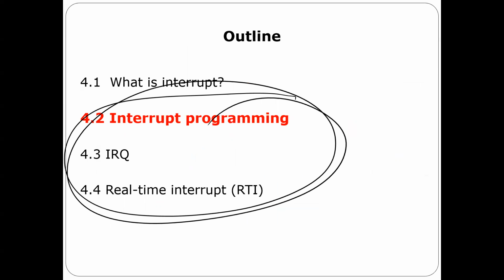if you compare it with what I did in chapter 3 in flashing the LED, it's going to be too simple now, because all I'm going to do is initialize, or program, the timer. I'm going to tell the timer, please timer, interrupt me every 1 second. That's it. So I'm going to write some instructions to program the timer. Then every 1 second, I'm going to write just one command, flip LED. That's it. So if you compare how I'm going to do flashing now with what I did in chapter 3, it will be much easier now.